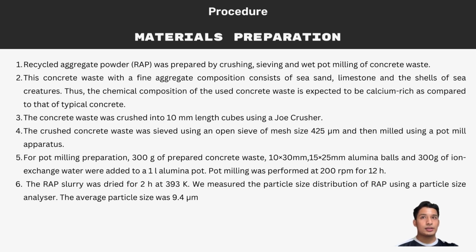This concrete waste with a fine aggregate composition consists of sea sand, limestone, and the shell of sea creatures. Thus, the composition of the concrete waste used is expected to be calcium rich as compared to typical concrete waste. The concrete waste was crushed into 10 mm length cubes using a jaw crusher.